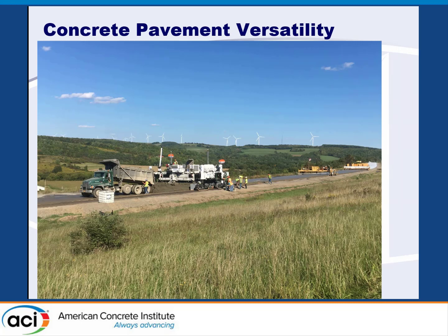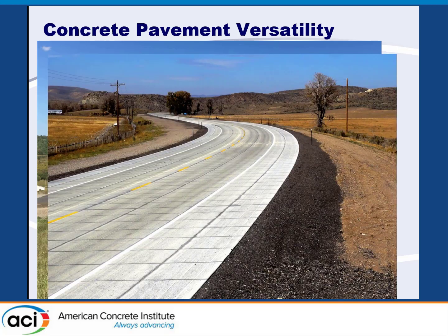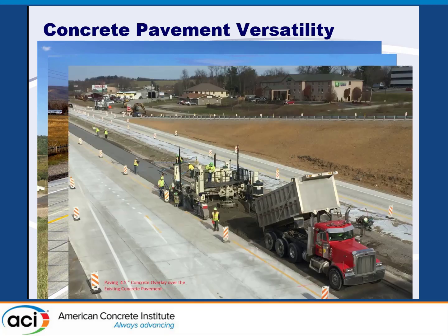But in addition to that, we can also do overlays, which Peter's going to talk about here in a minute. And overlays can be a whole different monster in what you can do with them. You can do thicker overlays that are unbonded from the subsection below you, or you can do thinner overlays that are actually bonded to the asphalt pavement or concrete pavement below it. And you can also do thinner overlays that have shorter joint spacings that can also reduce stresses as well.